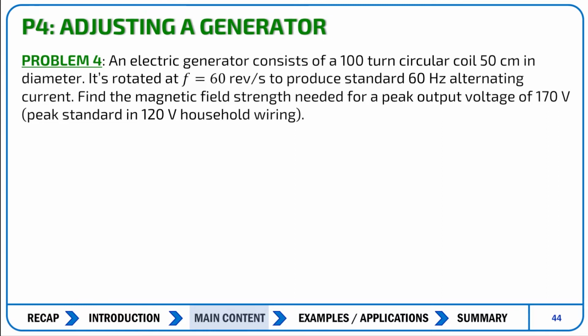Okay, so first we have to state some knowns and equations, and we also have to maybe draw a diagram just to understand everything that's going on here. So first, we can assume we have an electric generator that looks like this. This is going to be wires that lead to the load. It is going to rotate. So I have my planar axis here, and so we have rotation around this, and that rotation takes place at omega equals 2 pi f for the angular frequency.